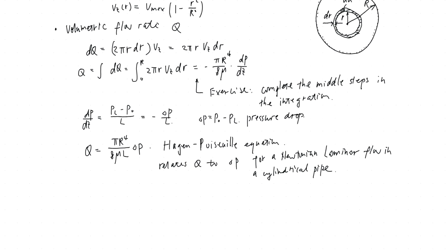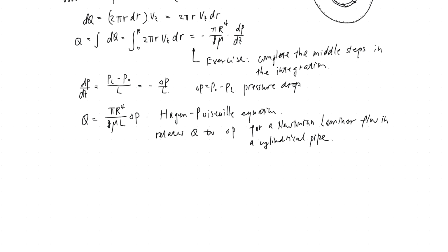And now let's just have a quick mention of why it's related to the capillary viscometer we mentioned earlier. You can see that Q is something you can measure, delta P is something you set up, and you know the dimensions, R and L of the pipe. So that's how you can use this relation to find the viscosity of the fluid. If it's a Newtonian fluid, you can just run a flow across a capillary pipe, and then you can estimate the viscosity. It's a pretty neat method.